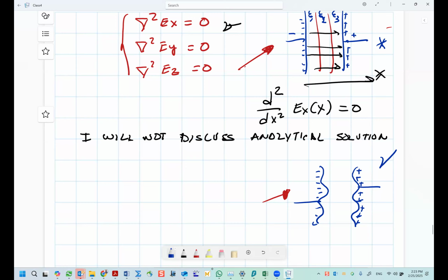The way the elements are decided, which kind of elements. Triangles are the favorite because they fit most curves, but they are not the most efficient. There are other ways. If you are able to guess the field and put the meshing in a way that the equipotentials are part of your meshing, you get a lot more efficient and more accurate results. We will talk about all these things when we get to finite elements, which is not too far.